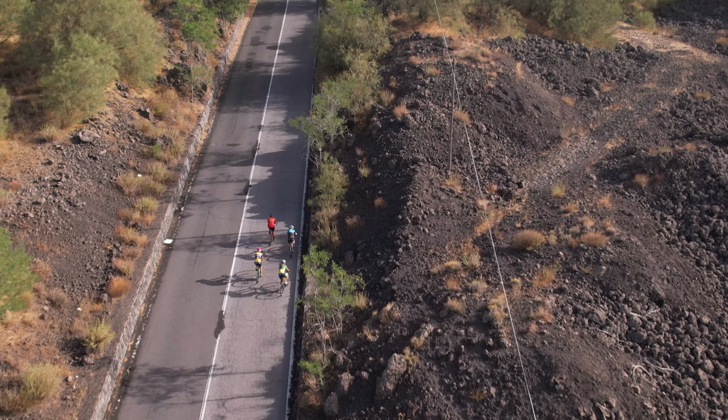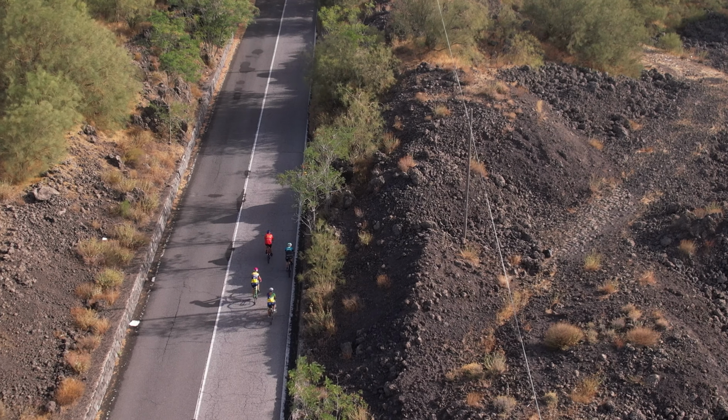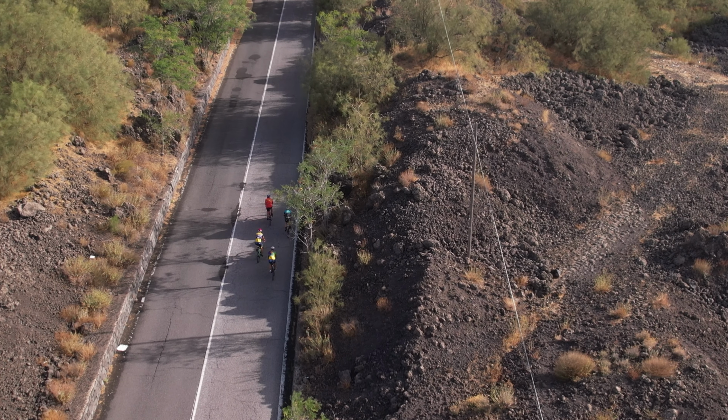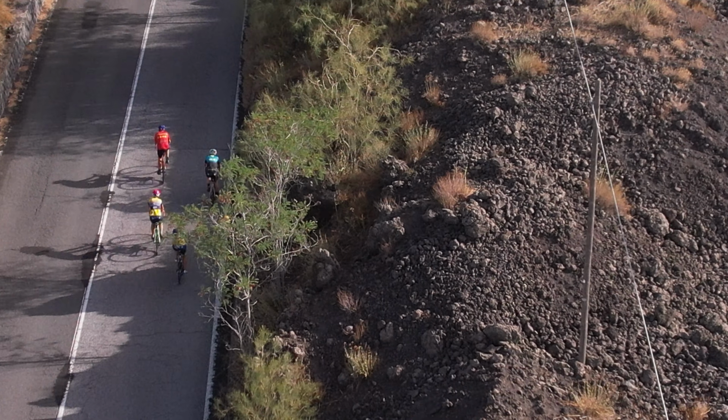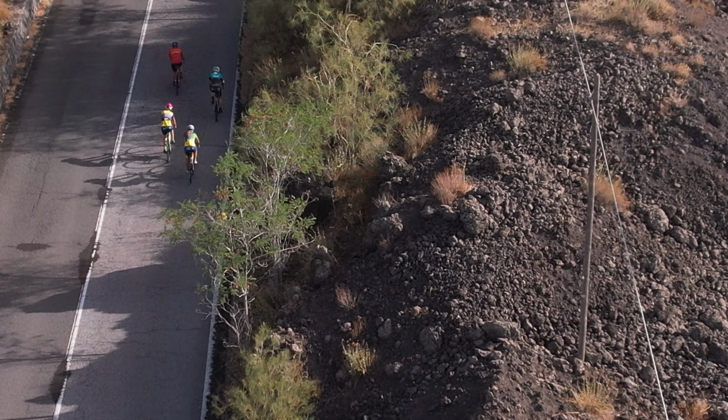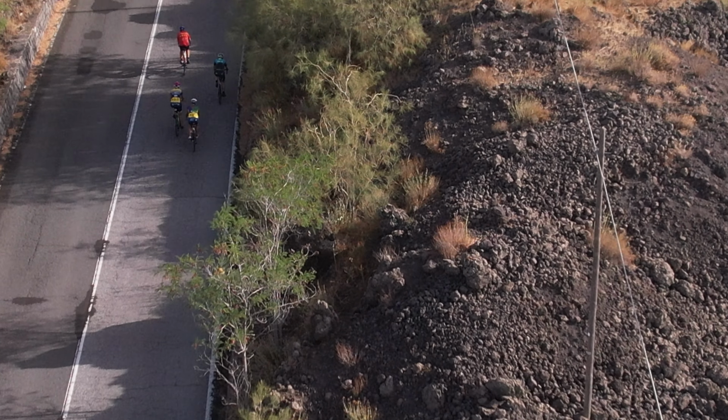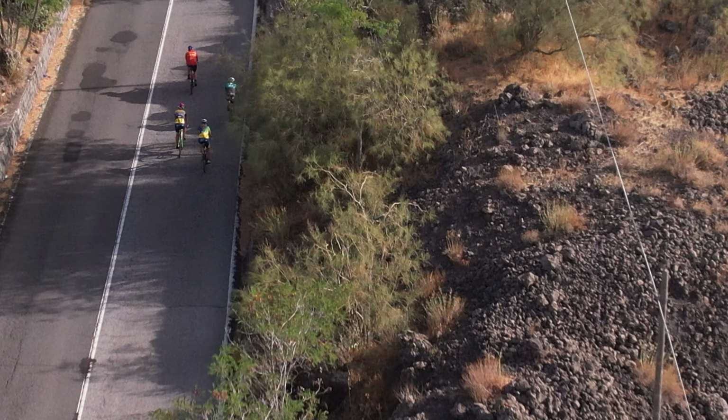Luckily the Focus Track modes are compatible with the excellent zoom capabilities of the Air 2S. Therefore it is possible to fly higher than the surrounding obstacles and remain relatively close to the action. Just remember that the zoom tools are available only in normal mode, but not in D-Log or HLG.